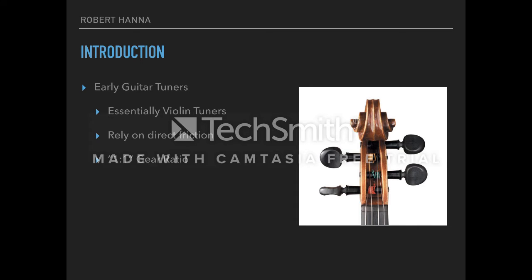So to start, early guitars, as early as the 16th century in Spain, used a similar tuning system to violins and violas used today, which is just simply a peg with a string wrapped around in line. So there's no gears, nothing to facilitate mechanical advantage. It's just simply a string wound around a piece of wood. These days probably use plastic as well. It relies on friction to essentially affix the peg and the tuner to the machine as well as to hold the tune. So you're really relying a lot on mechanical properties here.